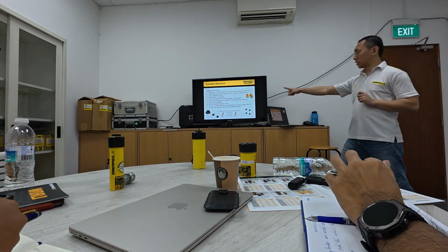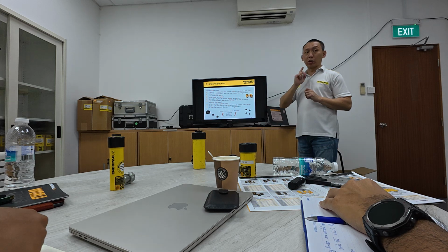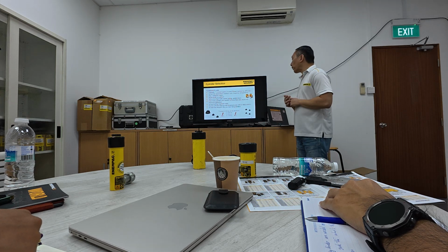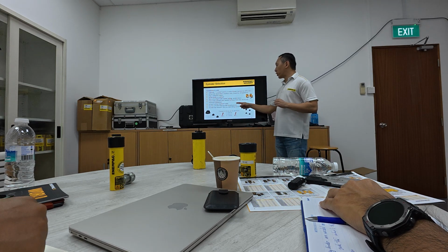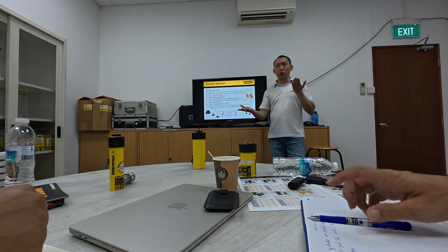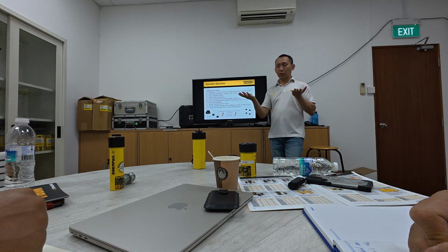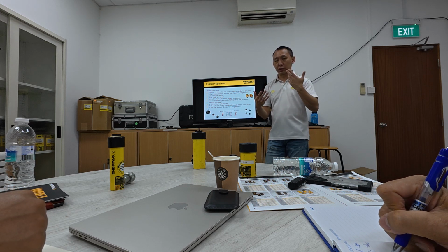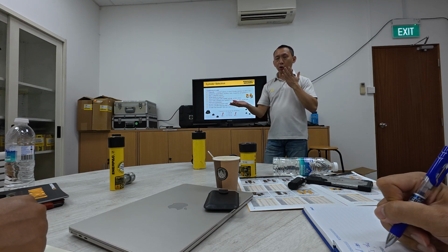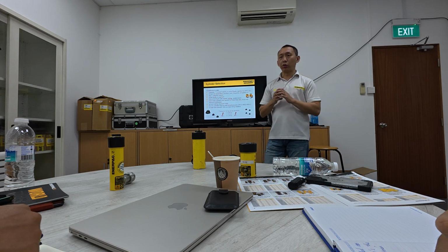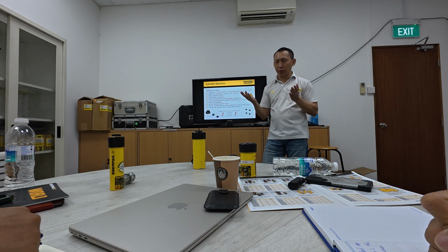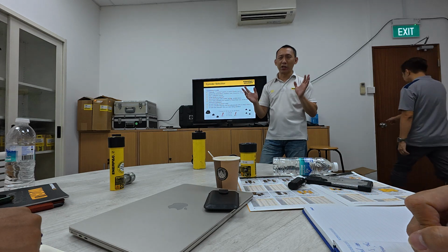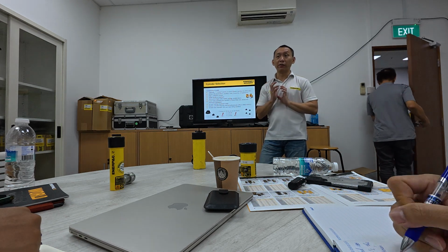So that's why the distance is very important if you're using more than one cylinder. And then just now I mentioned if the customer needs to lift the load, what you need to know is how long they need to hold the load. If they are holding a load for maybe half an hour, one hour, not too much, they use the load holding valve to do it.